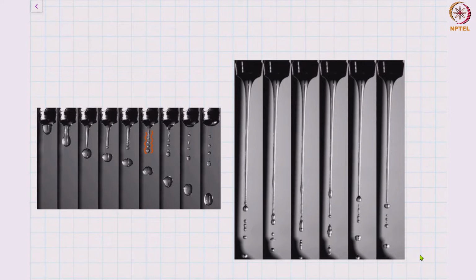Now, there is another interesting thing to note here: you have an undulation somewhere in this region, and as the jet descends, this undulation is carried forward, but at the same time it's growing. It becomes a lump here, and then a droplet, and here it's detaching from the thread. This process continues, and what you're seeing here is the Plateau-Rayleigh instability, or the Rayleigh-Plateau instability. Plateau originally studied this problem for a falling jet, and Rayleigh extended this analysis to study the stability of a filament, meaning a filament which is not actually moving. There's no velocity inside the filament.